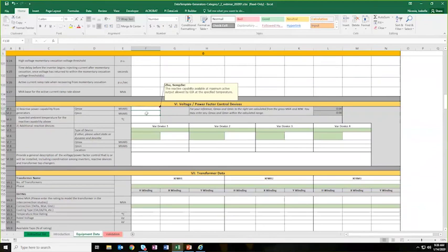We expect they are within that rating. If they are not, we'll ask the generator why. If they're within the rating but somehow below it, that depends on whether it meets the requirement. We'll also compare this Qmax and Qmin, together with all the other VAR devices and the total reactive capabilities, to the VAR requirement in the GIA. Different generators have different requirements. Yes, the generator interconnection agreement.